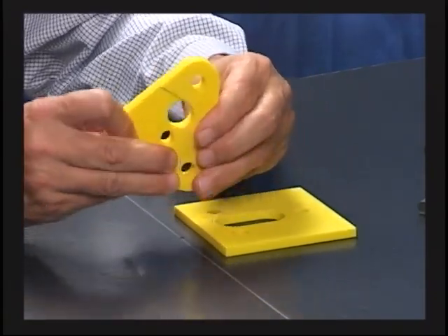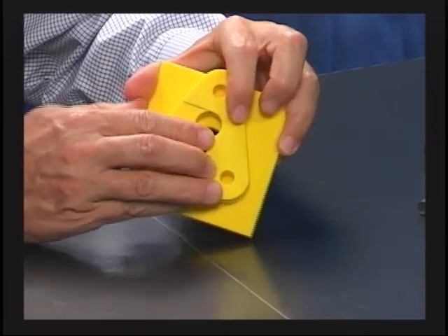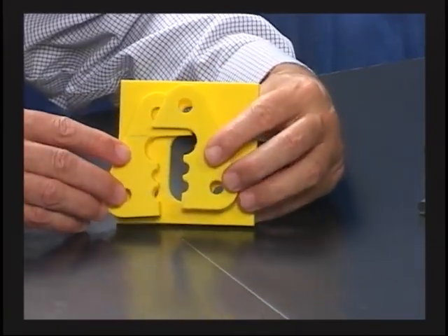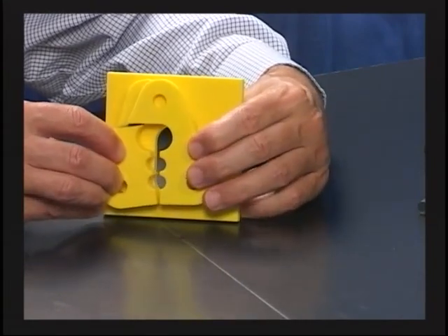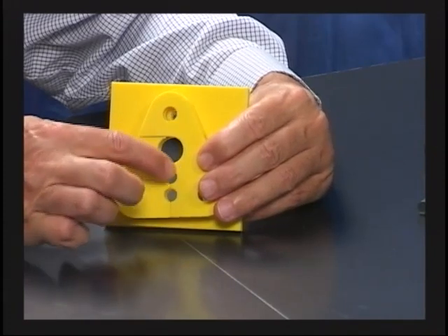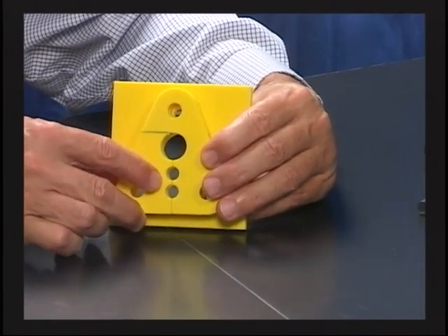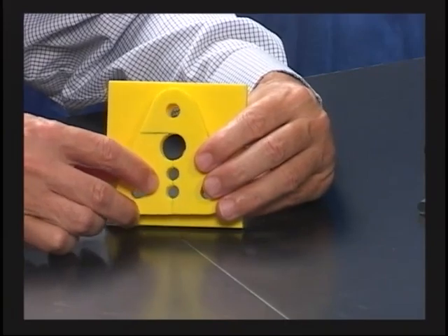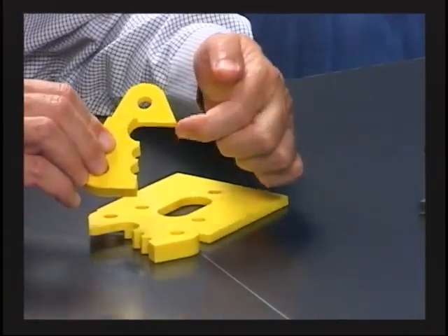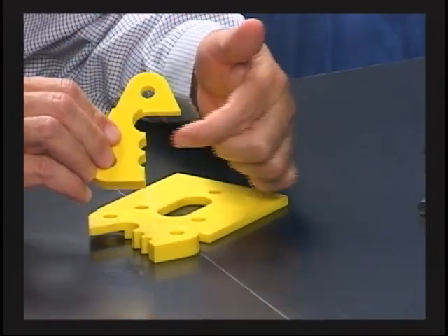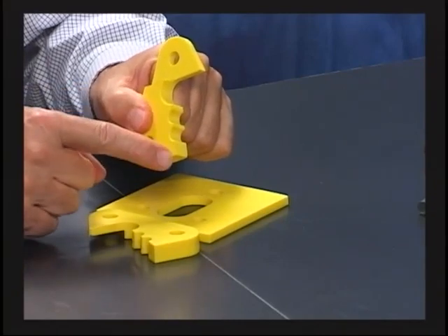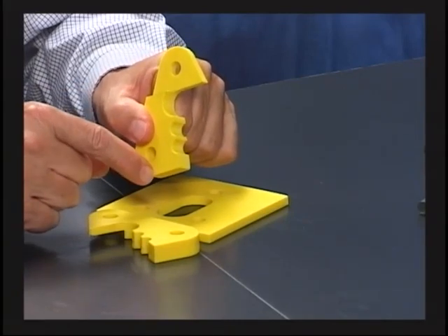First of all, they're coming together on the bulkhead, so that was my primary face. And then when they came together, you see how they locate one to the other? I'm going to push it tight up against that face. You see it comes right up against that face. That I call my secondary datum. And then what stopped the part up and down? I could have picked this top face up here, I could have picked this one here, and what I did is I picked this as my tertiary. I picked this one as my secondary datum because that was the longer one.